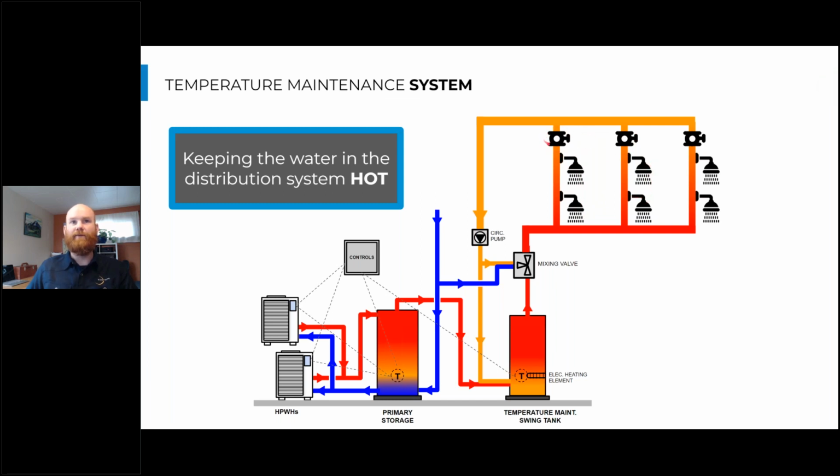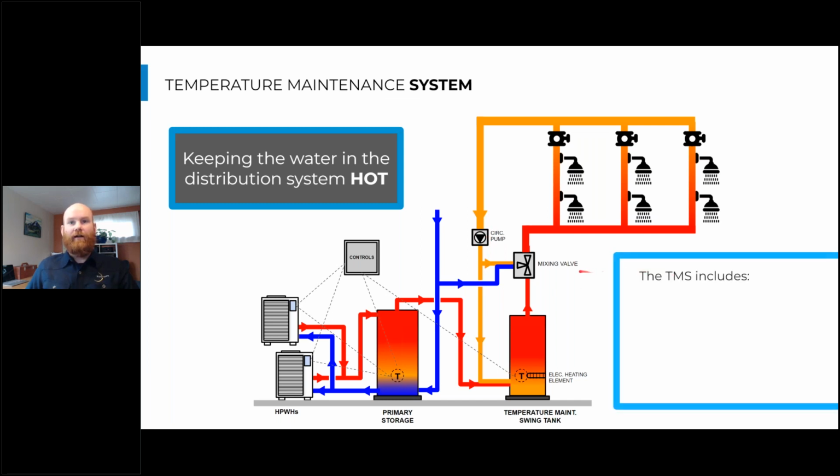We typically have some way to balance each one of those loops, and then we collect them all at the top and route that back and put a circulation pump on that to draw water through that piping circuit slowly.